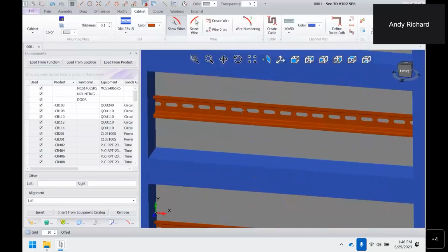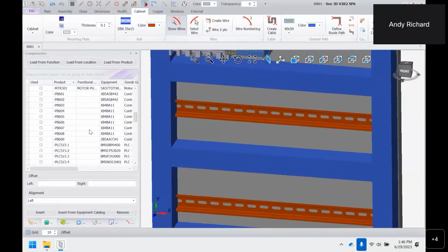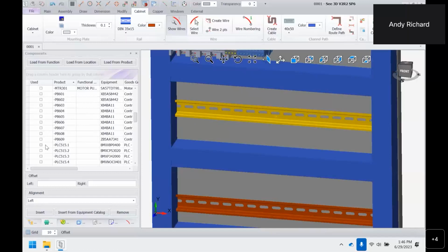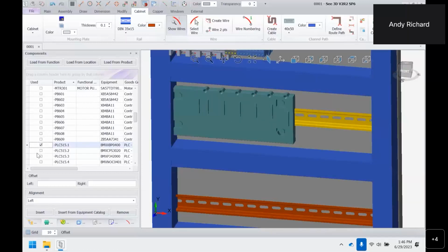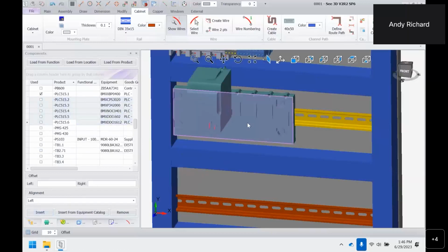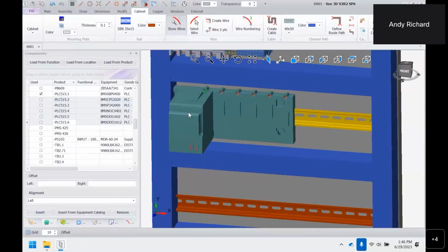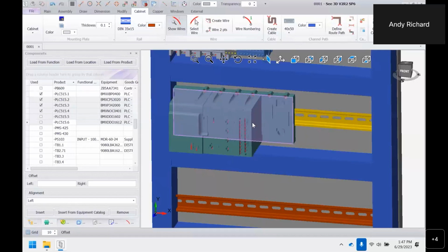Now, going back up here, we have our PLC. So I'll select my DIN rail. I'll insert my backplane, and that comes populated. Now with the rest of the cards, I'll select those, click insert, and then I have a backplane and snap points to place them. So I have slot 0, 1, 2, 3, 4, 5, and I can just place them quickly, and I keep track because I know now I'm on the network card. I can just know that I need to put it there. If these were in the opposite order, I could just place them correctly, so I could switch those around.